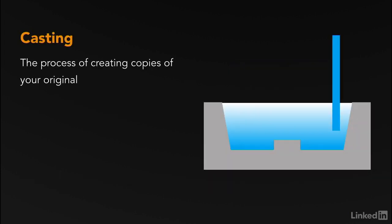Casting is a reproduction of your original master part and refers to the process of filling your mold cavity or cavities with material that hardens and is then removed from the mold once cured into a stable state of solidity. In many cases, casting can be repeated multiple times with the same mold. A rule of thumb for ease of prototyping molds is that if your final parts are hard, the mold should have some give. If your end parts are soft, the mold can be hard.